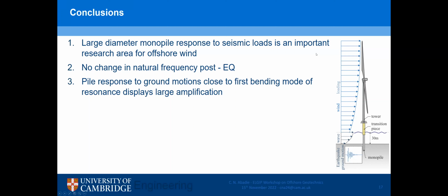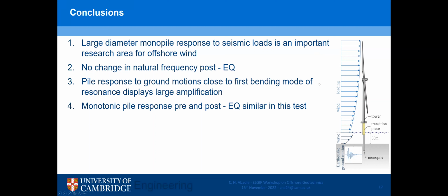Pile response to ground motions close to the first bending mode of resonance display large amplification, but quite reassuringly, the monopile response to monotonic load was quite similar post and pre-earthquake. In this test, again, that needs to be extended to larger geometry and saturated soil.